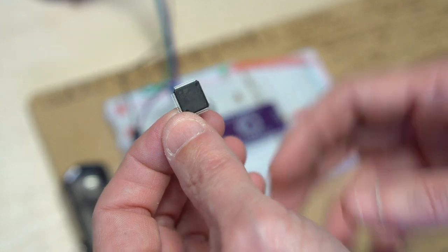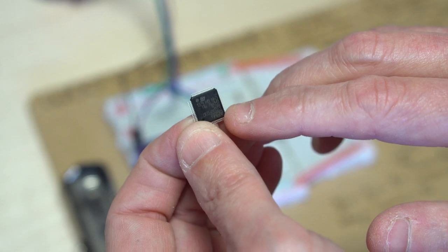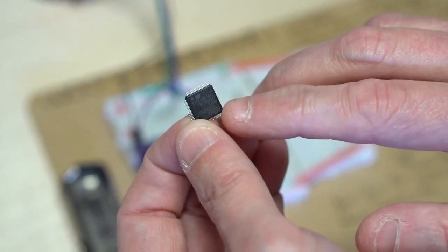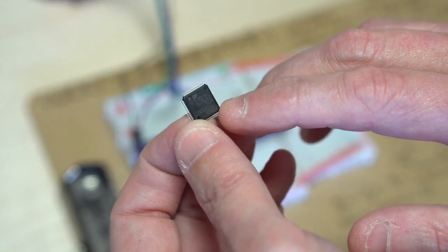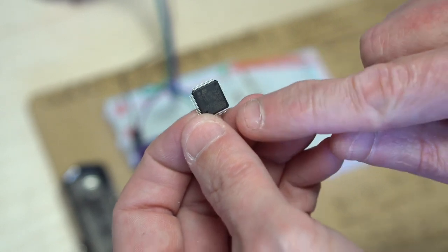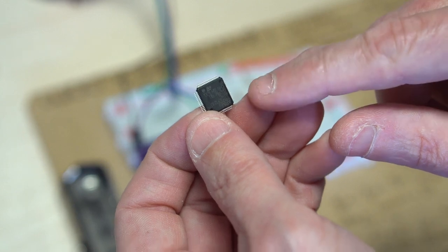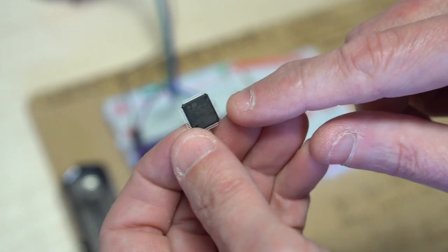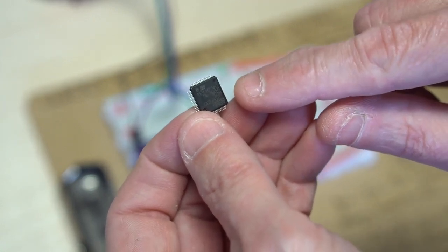In this video, I'm going to show you how to change the clock speed of the microcontroller from 8 MHz to 48 MHz. This is an STM32F030 microcontroller. The STM microcontrollers have an internal clock and an external clock, and each of these clocks have a low speed and a high speed. The high speed internal clock is the HSI, and the low speed internal clock is the LSI.